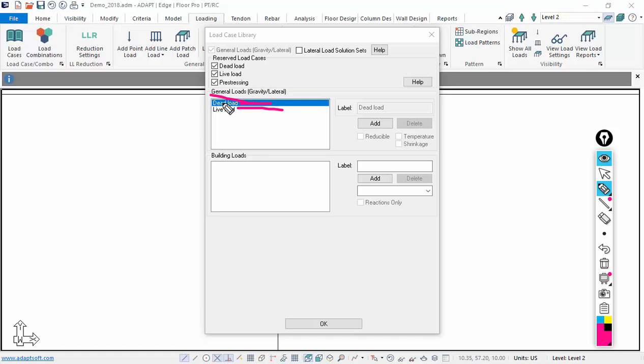Live load reduction can be done for horizontal elements using subregions or skip patterns over here. We do have additional videos that touch on that. This particular reducible tag here is really only for vertical components like columns, and it specifically applies to design of columns with reduced live loads. So for this example, we're just going to set the loads as dead or live.